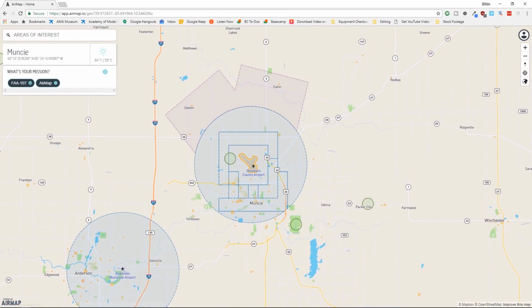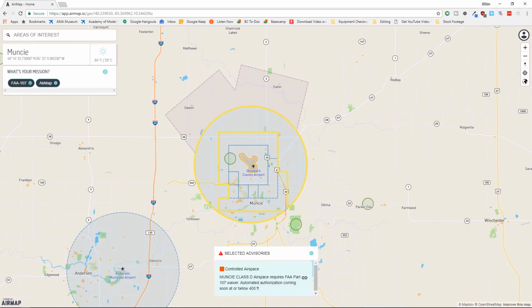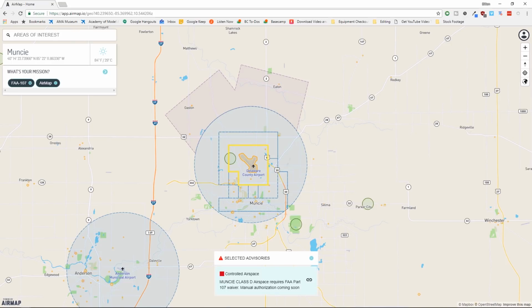To construct the UAS-FMs, the agency divided the area surrounding each airport into a grid of 1 mile squares and worked with local controllers and airport managers to determine how high a drone could fly within each of these squares. On the approach and departure routes, that altitude is 0. However, elsewhere within the airspace, the altitude rises to 100 feet, 200 feet, or even the 400-foot maximum established by Part 107 regulations. The altitudes indicated on the UAS-FMs do not give automatic permission for drone pilots to fly in those locations. They merely indicate where operations can occur without additional safety analysis. You still need authorization to enter that controlled airspace, just as a manned aircraft pilot does.